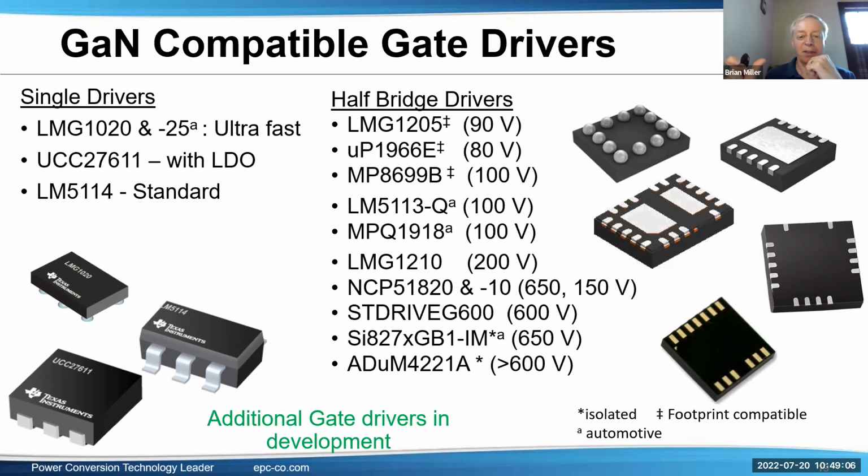Many controllers use the inductor, which could also be a transformer, to measure, and that's pretty benign to the GaN FETs. So I'd say in the switch node somewhere is probably the best place for it because it gives you the widest array of gate drivers without affecting the power loop and right near the FETs. But yeah, feel free to write in with specific requirements or a schematic or so forth.